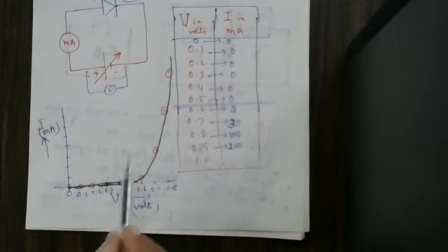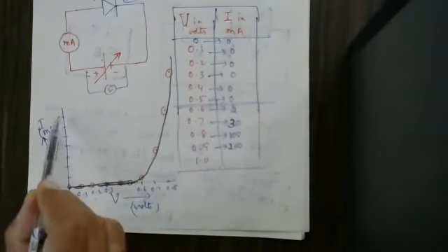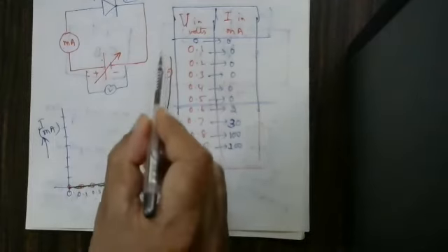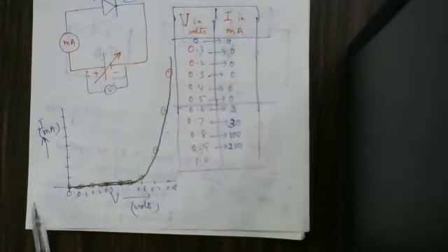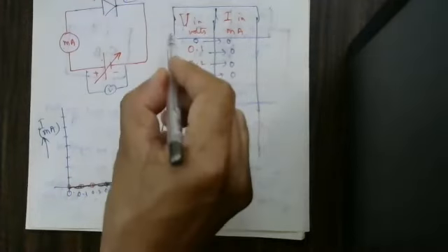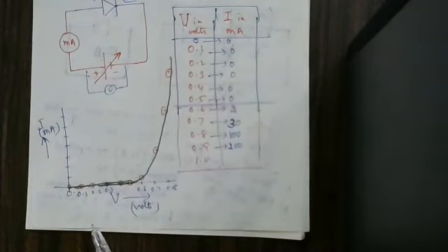This is the practicals. Whatever I taught is the practicals concept only. You are supposed to do all these things in your practicals. Voltage versus current, we have to plot. Whatever graph we are getting, you connect all these points using a smooth curve. You should not draw like this. No. A smooth curve we are supposed to draw. This curve is called the forward bias characteristics curve.